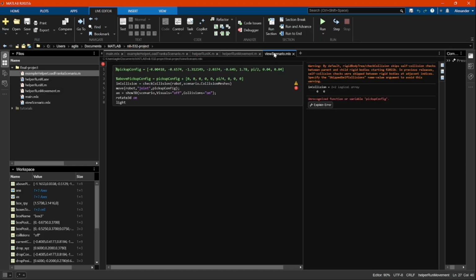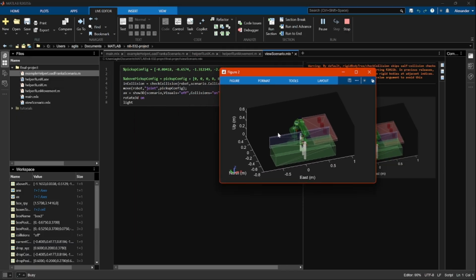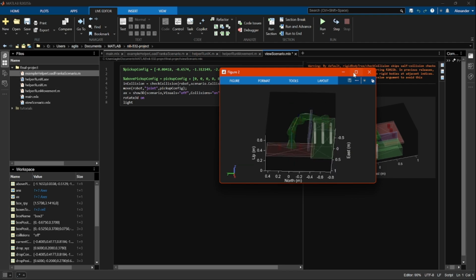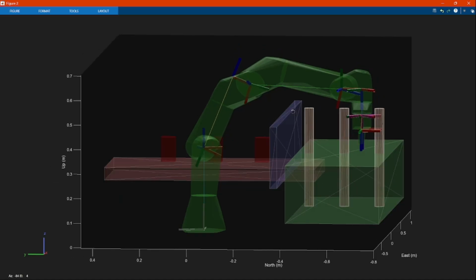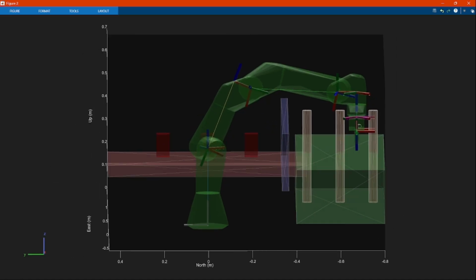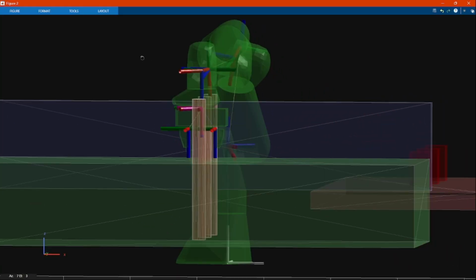This final helper script was just a debug tool that you might find useful. If you run into an error, it will let you visualize the robot in the case of collision. This shows all of the different collision geometry that the robot has. This is the problem collision box that I had to edit in the robot import script here.